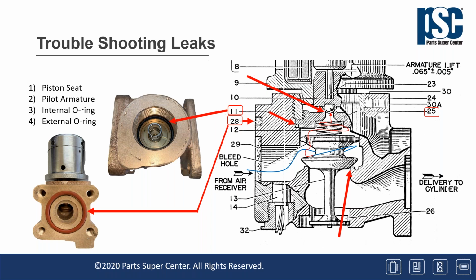To detect the leak between the coil housing and the valve body, you can often wrap a piece of paper around it like a dollar bill. If you can't determine exactly where the leak is coming from, you can do that and you'll actually see the paper deflecting. Or you can use a leak detecting chemical as well, like Snoop.